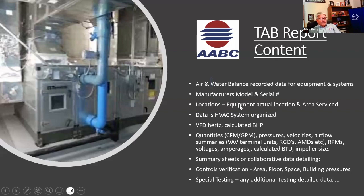TAB report content: air and water balance recorded data for equipment and systems, manufacturer, model and serial number, locations. The data should be HVAC system organized, meaning we shouldn't have all of the outlets in one section and all of the air handling units in another section of the report. What air handling unit serves whatever outlets or systems should be, say, pages 10 to 20, and then 21 to 30 should be another HVAC system.